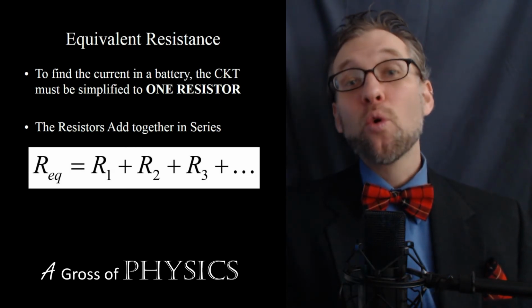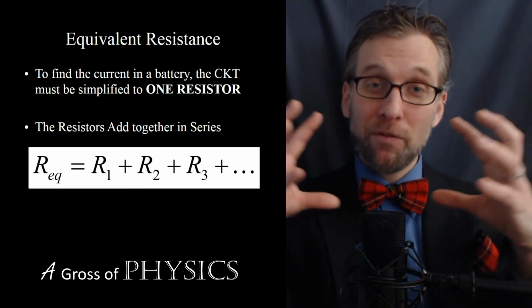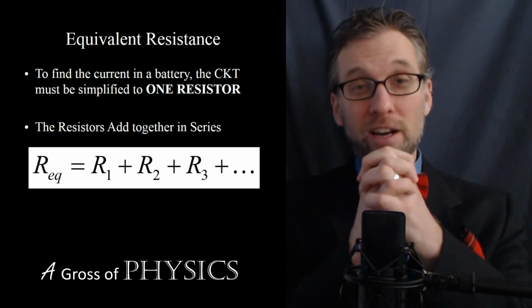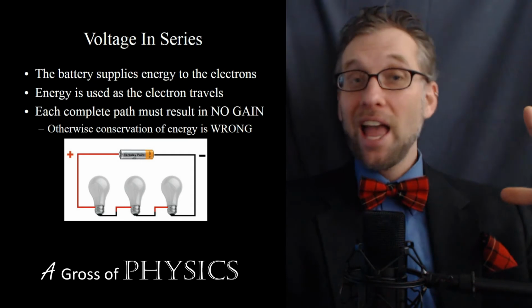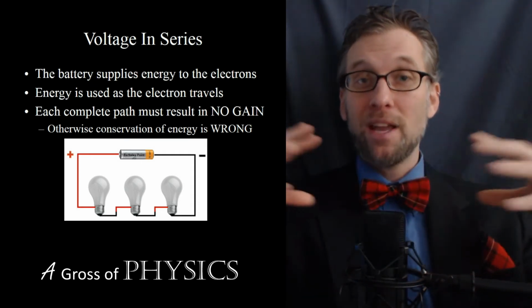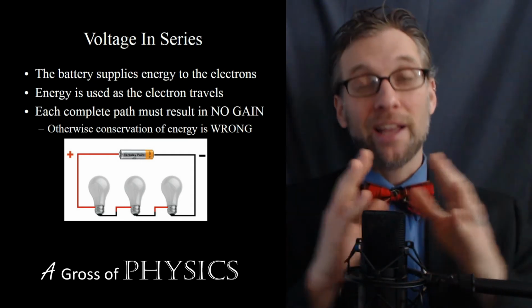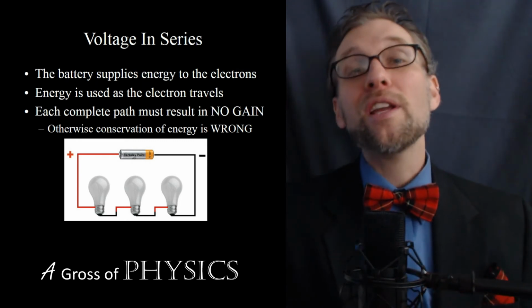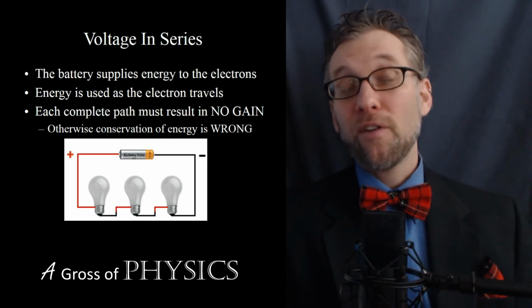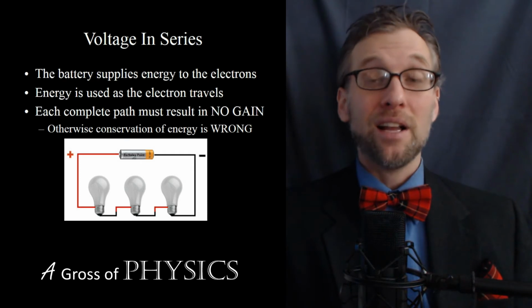Now I think of this as an accordion method. And what we do is we simplify the circuit, we smush it together, we find an equivalent circuit, and then we expand it back. And we may have to compress it again and expand it back and compress it again, kind of like playing an accordion. So the accordion method will allow us to simplify circuits and then expand them back to analyze them.